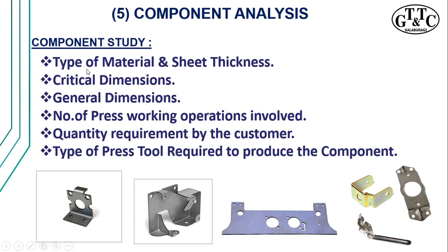The first one is the type of the material and the sheet thickness. It's very important to understand because everything depends on the material of the component and the sheet thickness. If you want to calculate the cutting force, clearance, all the press tool calculations are mainly focused on this particular platform, that is, the material of the component and the sheet thickness.